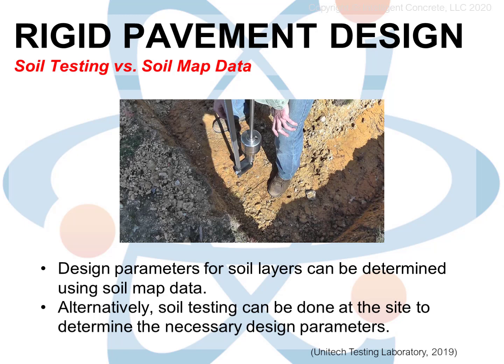If you remember a few slides back, very nearby was a soil listed as a kettle gravelly loamy sand, meaning it contains a significant fraction of gravel, which does not appear to be present at our site. The takeaway is that soil types can and do change dramatically over even a short distance. Sometimes several different types of soil intersect and overlap at a building site, further compounding potential design and construction issues. Today, though, we don't have to worry about that.